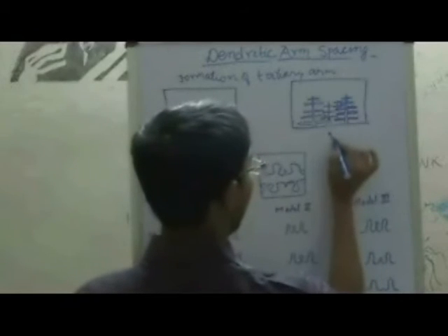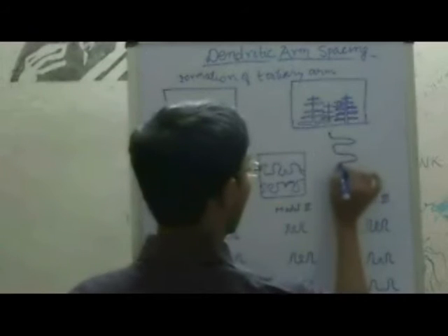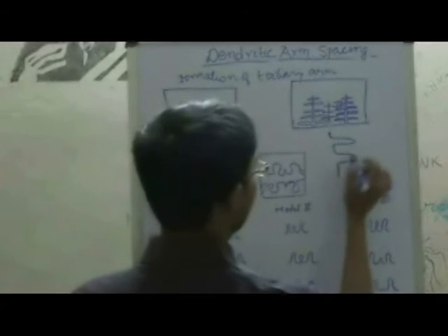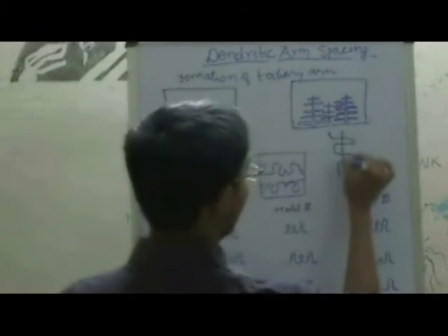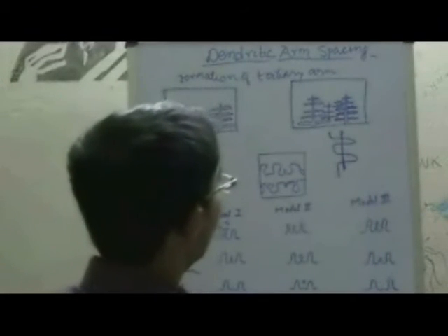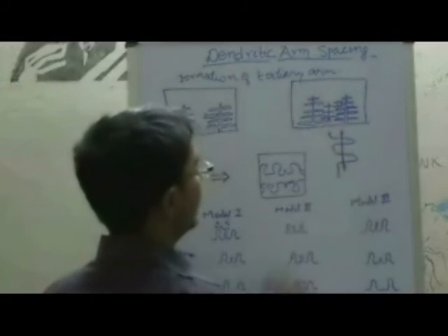This is what we call constitutional solidification: solidification depending upon the composition, not due to temperature. Therefore, the driving force for this process is constitutional solidification, and this is overcome in the dendritic case by the formation of a new branch.